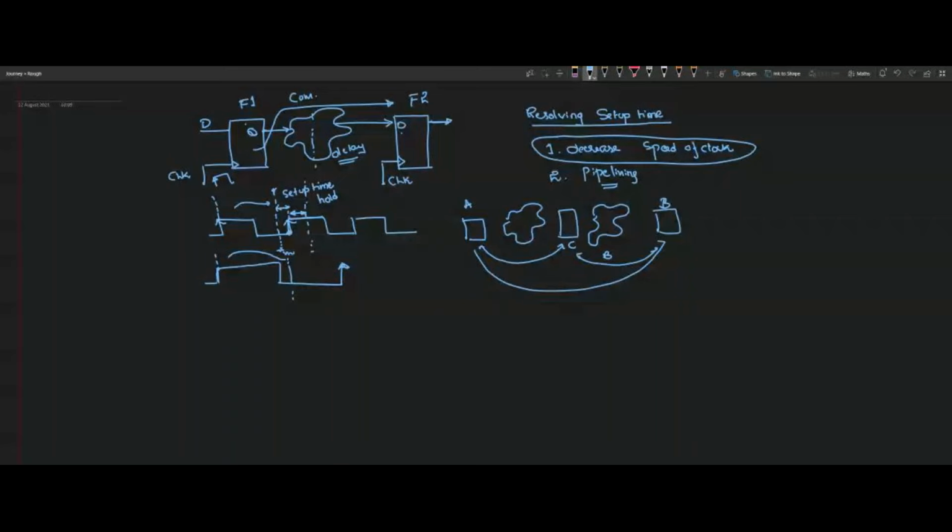Yes, actually, after synthesis of your FPGA design, you will see the F max of the design in the synthesis report. That is the maximum frequency with which you can operate. We have something called the critical path, which is the longest combinational path we have, and usually the timing violation is seen in the longest combinational path.